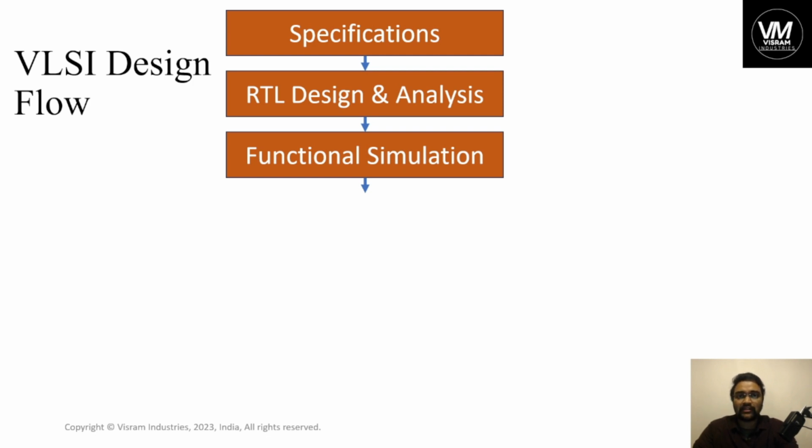Test benches are very much required in this entire design flow, because whatever script you have written in the HDL language needs to be tested on a simulation platform. EDA tools have a simulation platform, and there the test bench is attached to the primary source file, the primary RTL file, and it verifies the input and output processing, how this code is working. You have already seen that test bench working. The waveforms, timing simulation diagrams, charts and windows are all simulation steps.